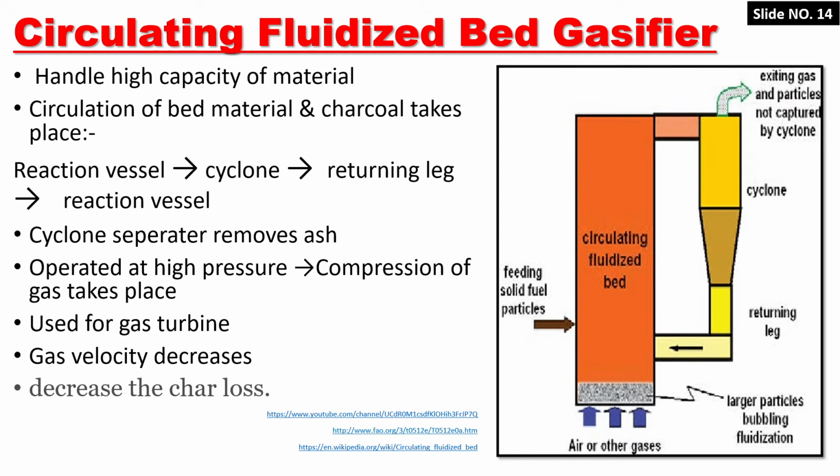A disadvantage of this type of gasifier is that the size of fluid particles determines the minimum transport velocity. Heat exchange is less efficient than in a bubbling fluidized bed system. Temperature gradients occur in the direction of solid flow.